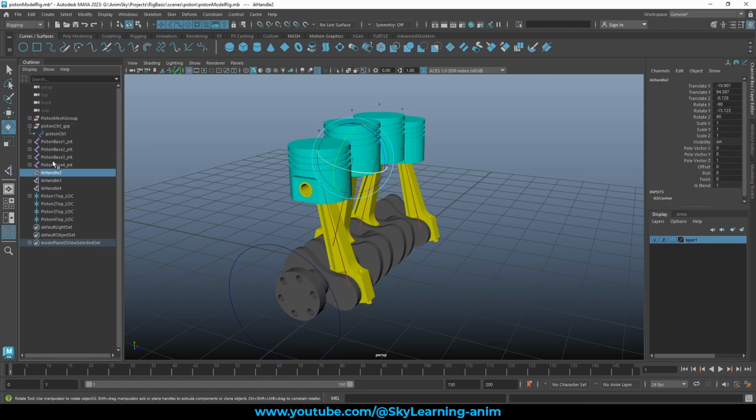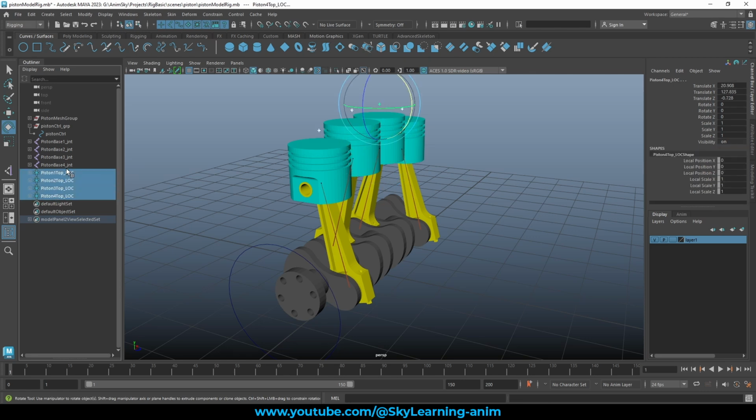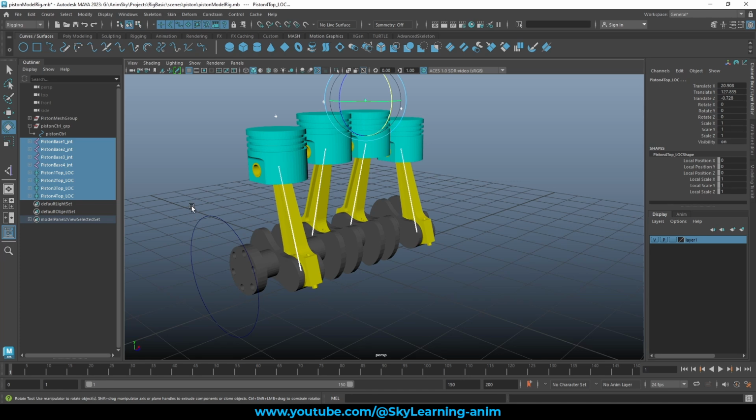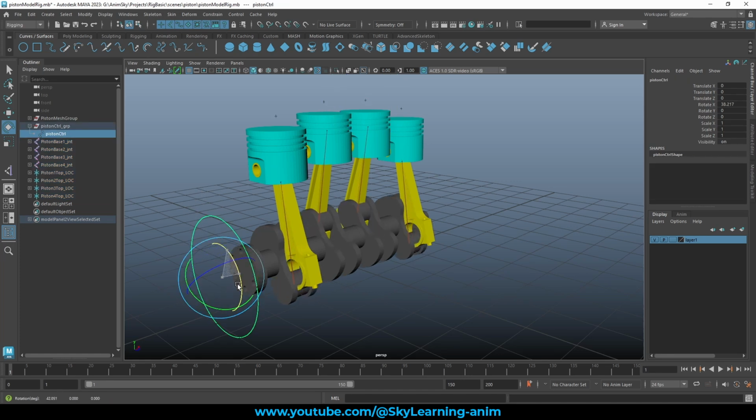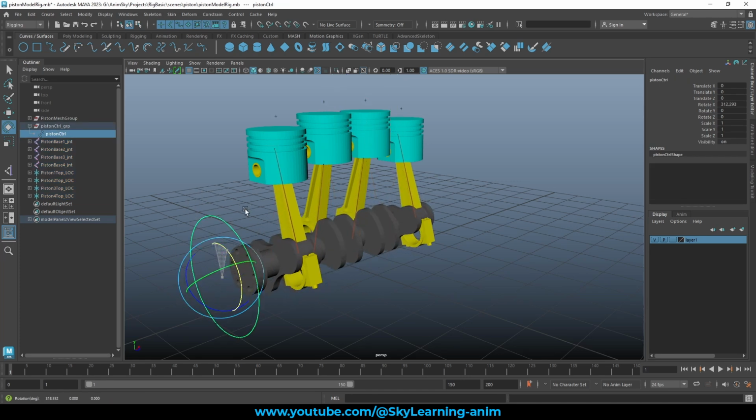So okay, let's just clear out everything in a clear manner. We can child this IK handle to the respective locator. 3 goes under 3, 4 goes under 4. So this is now a locator group, this is the joint group. So now the end part, okay, let's test it out first, and all of the 4 joints are working as we wanted.